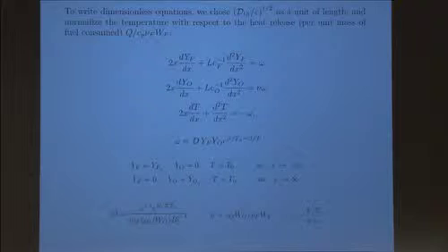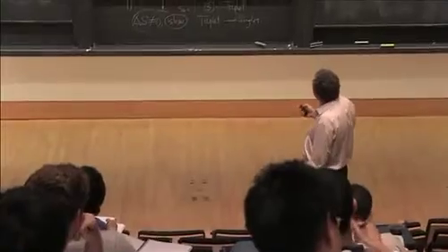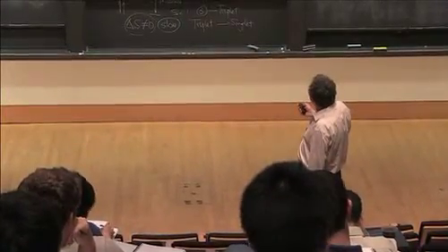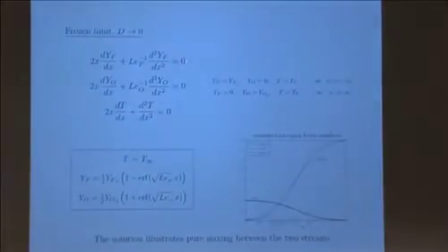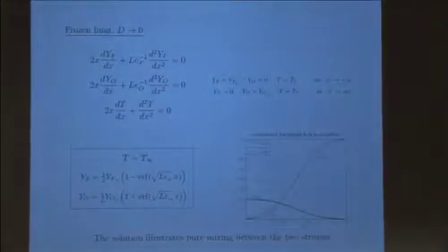We will start with two limits that I want to look at. The first limit is when the Damköhler number is very small, goes to 0. That's clearly not the Burke-Schumann limit. It's the opposite limit. It's what we often refer to as a frozen flow. In other words, the chemical reaction is frozen. That's where the name comes from. And so if D is identically 0, then there is no chemical reaction.